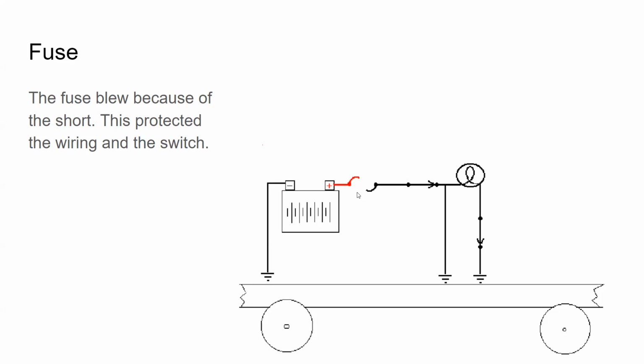And instead of popping like this in your fuse box, some of your wiring harness will melt down, just like that little chunk of fuse did. That's not what you want. So never, ever, ever replace a fuse with a larger size fuse than what it's supposed to be. That fuse is there to protect the wiring harness and to keep your car from catching on fire.